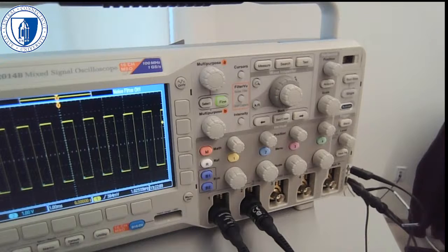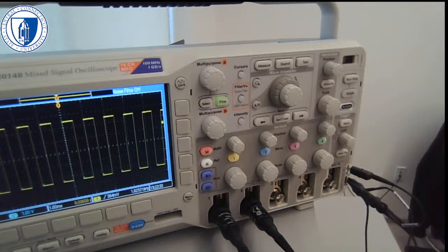It's a bit hard to see, but there are actually graph lines on the screen. Just dotted lines, and each of those vertically is currently 1 volt per division. Right, that's what this is saying here for the blue channel. And I think there's 1, 2, 3, 4, 5 divisions. So the peak to peak voltage is 5 volts.